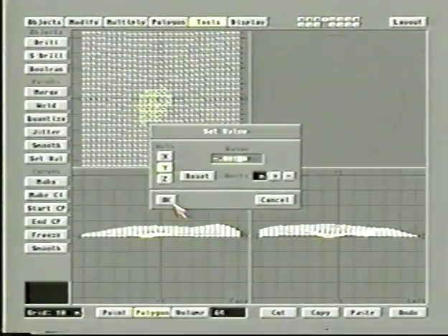By putting the ground at -1 millimeter, when the road object loads in, it will be right on top of the ground, which is quite handy because it means I don't have to push it up or anything like that. So that's all I'm doing here is putting it 1 millimeter below, so when I load in other things like houses or roads, it'll work properly. So we set it to there, hit OK.